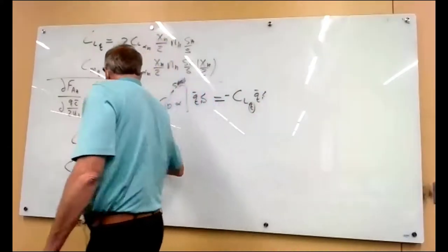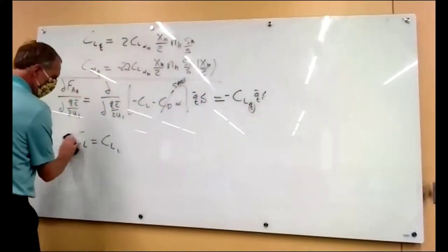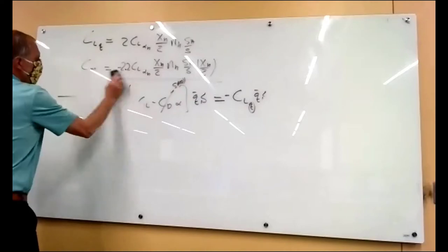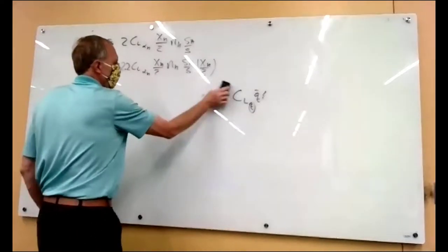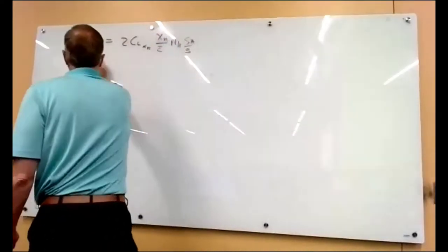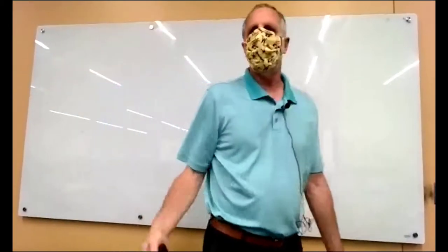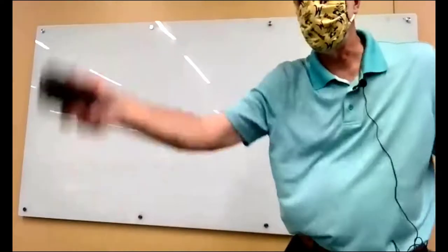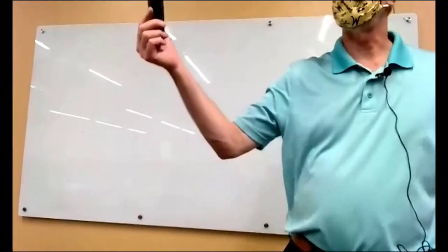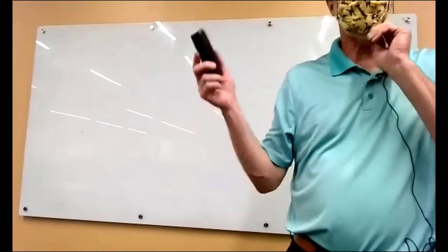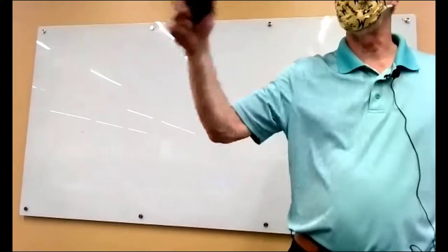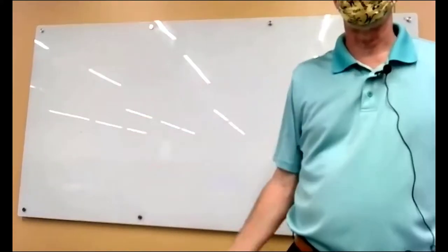So all these formulas are in the book. Again, I won't expect you to memorize them. I do want you to know the effect and be able to explain it. So I might ask you to draw a picture just like I did and say, well, if you have a positive Q, the tail's moving down, which increases the angle of attack of the tail, and that angle of attack change depends upon Q and the distance back to it, right?